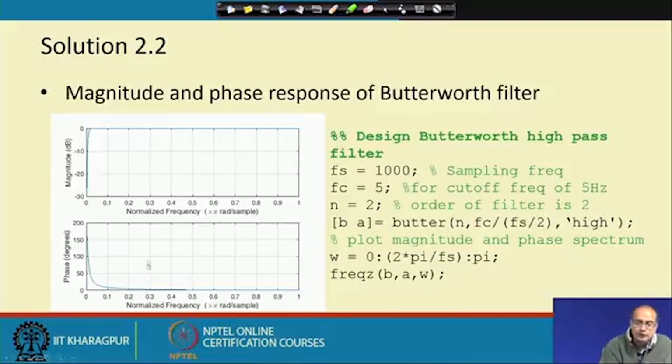So, if you recall the previous experiment, when we had a single 0 on the real axis at radius 1, both the phase and the magnitude responses looked much better. Okay. The only thing, the phase response probably was better because it was a linear one. However, we also need to keep in mind that here the order is 2.